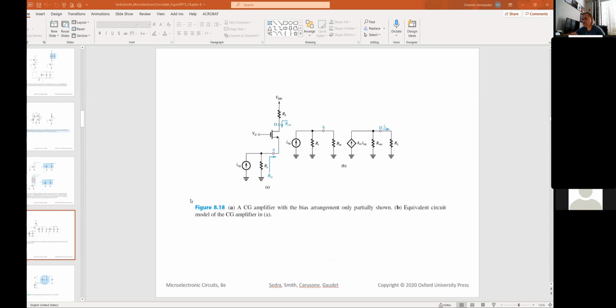So now we're going to have in between the load, and here we're showing it as a resistor, but that is our original load, this box here, and that box is the common gate that we have biased with some gate voltage. Again, these are biases that we can generate with the current mirrors and current steering that we talked about last time. And we have the input into the source and the output out the drain.